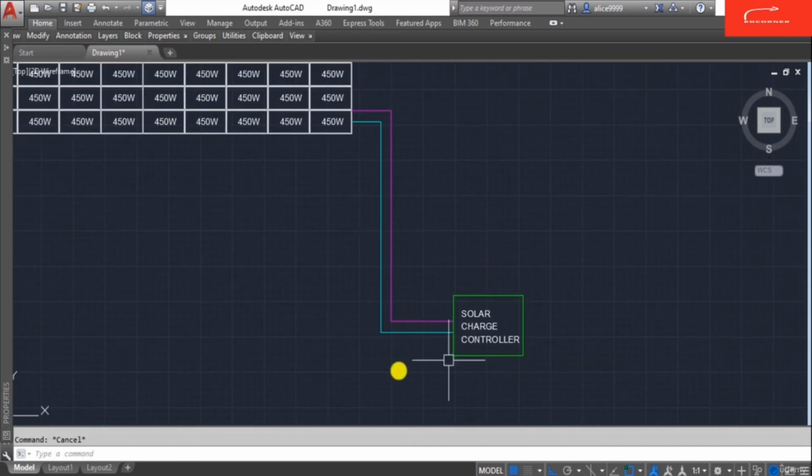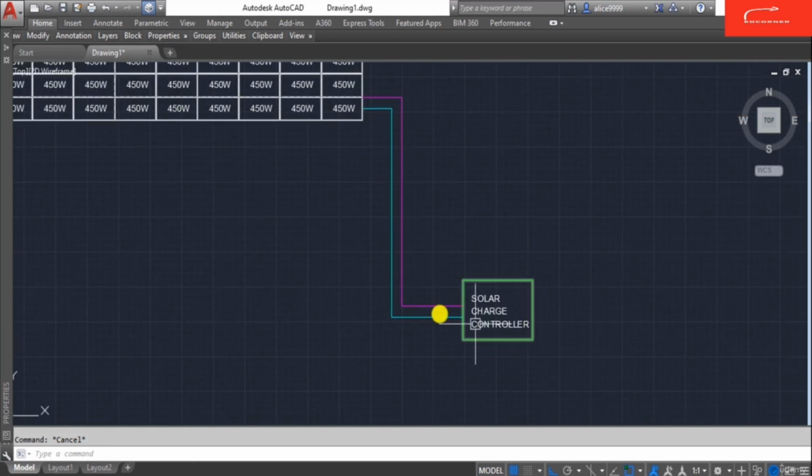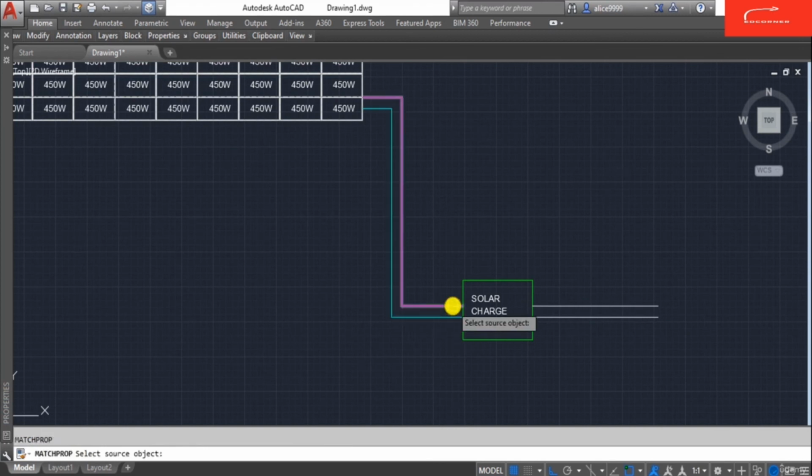The solar charge controller takes the command. The solar charge controller regulates the voltage and current coming from the PV panels going to the battery and prevents the battery from overcharging and prolongs the battery life. So the command for power saving into the inverter must come from the solar charge controller. From the solar charge controller, there is the cable like this.